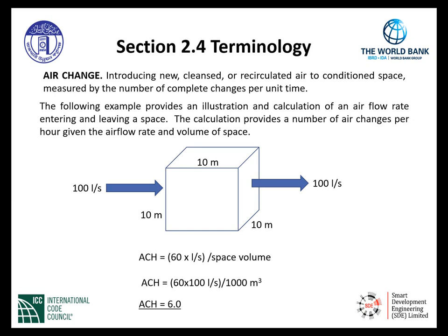As seen, we have a volume of space that essentially measures 1,000 cubic meters. We have an airflow rate entering at 100 liters per second and an airflow rate leaving at 100 liters per second. The air leaving would be, in fact, the exhausted air, while the entering air is new air, completely cleansed or recirculated to the conditioned space.